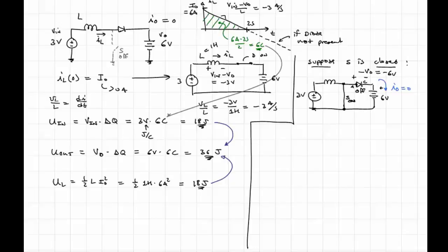Right now what we need to do is just look for a mechanism by which we can put some energy into the inductor before we connect the inductor through the diode up to the output, and leverage the ability of the inductor to push charge uphill, potentially. So what do we have from the vantage point of the inductor here? What does it see? It has a voltage VL that is equal to simply the input voltage.